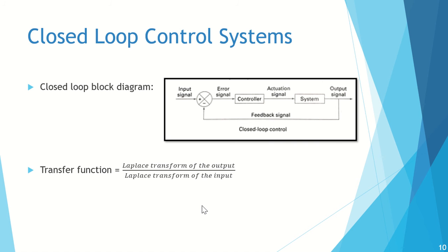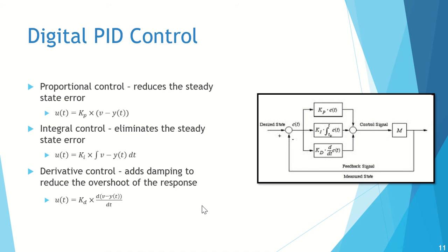And then we've got a closed loop control system which is controlling the pitch and the roll, and they've got PID controllers inside them, and these PID gains need selecting. One of the things that occurs with an aircraft is as you change airspeed you need different gains, so you need to have different gains for different flight conditions. So it's the same with this.